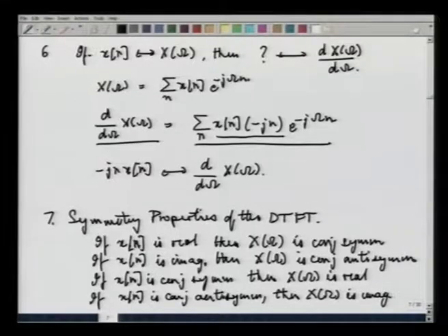As before, it yields interesting and pleasant results, like if x[n] is both real and even, then X(omega) will also be even and real, and several other similar results that one can derive at one's leisure. So much for the symmetry properties. Now, we introduce a notion which is unavoidable at this stage and which could have probably been introduced earlier, a notion of convolution of a different kind.